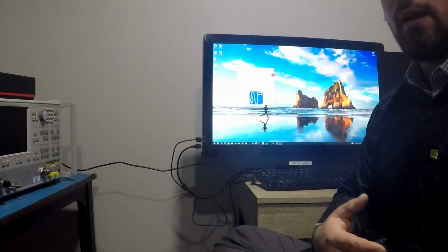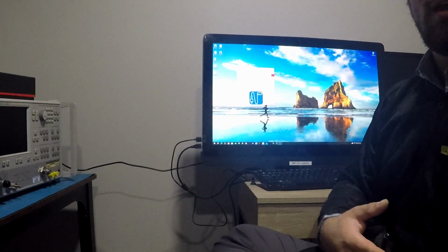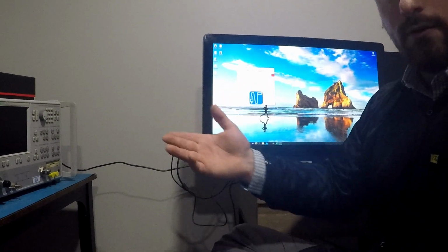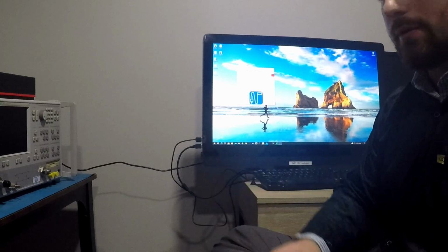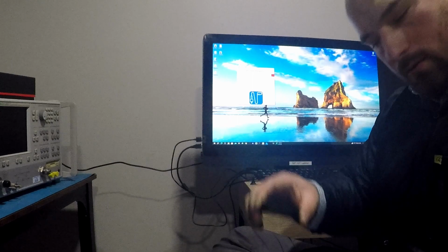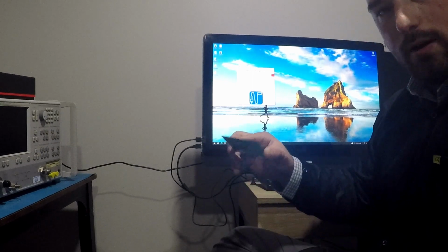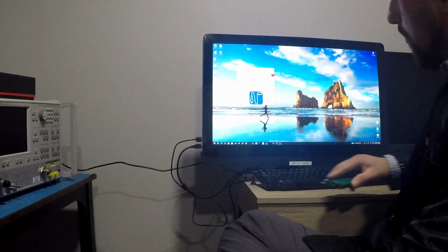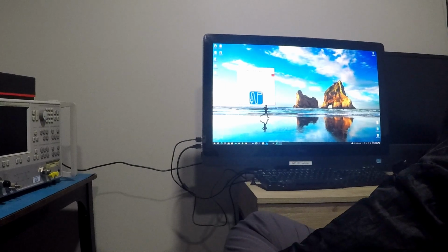That way I can optimize each separate board, do a quick spin, and get it within a week instead of 9 to 12 weeks and several thousands of dollars when you're doing mixed materials. It was designed to be BGA reflowed to the DC board. That didn't quite work, so we went a different route.